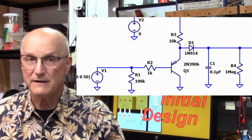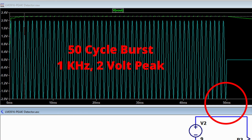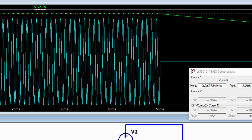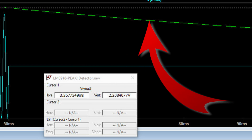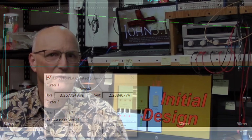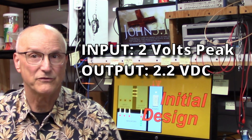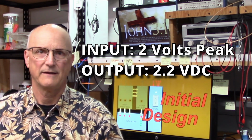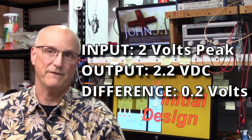Now, I've simulated this using LTspice. There's a 50 cycle burst of 1 kilohertz 2 volt peak signal on the input. This stops at 50 milliseconds. The output reaches 2.2 volts in about 3 milliseconds. Notice also how the output trails off slowly. We have 2 volt peak on the input and 2.2 volt DC on the output. We will have to accommodate this 0.2 volt difference in the stuff that follows.